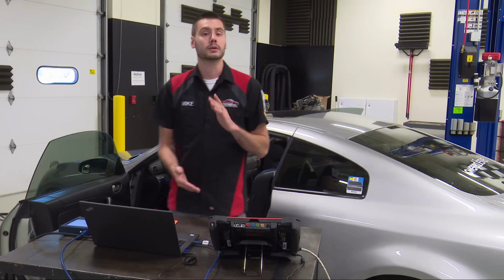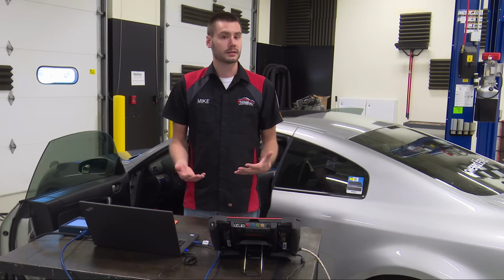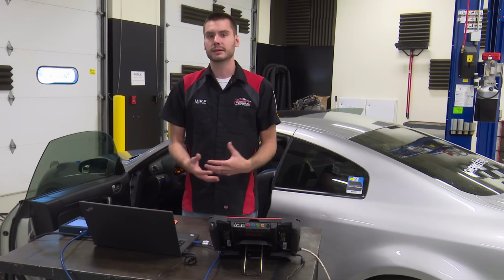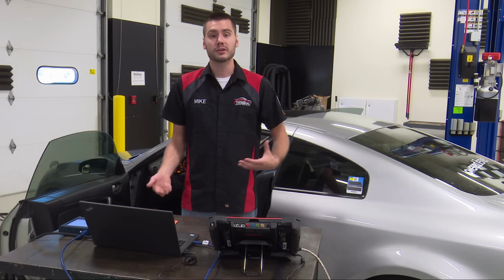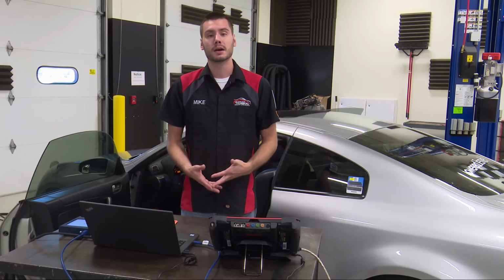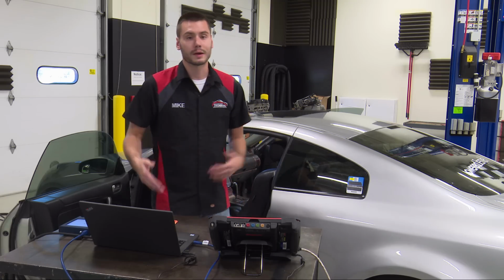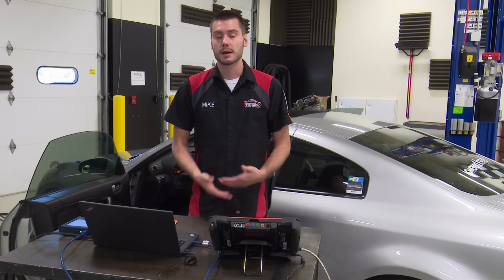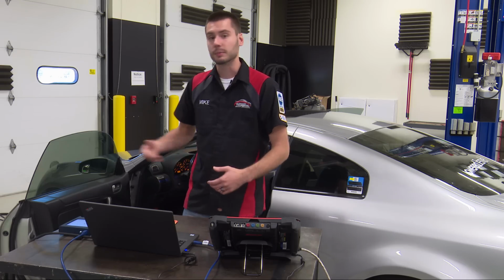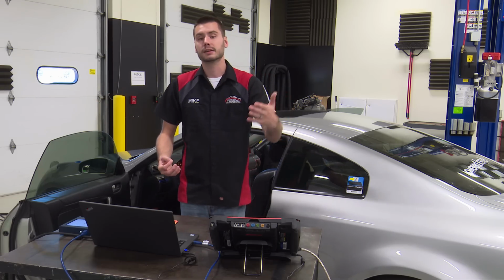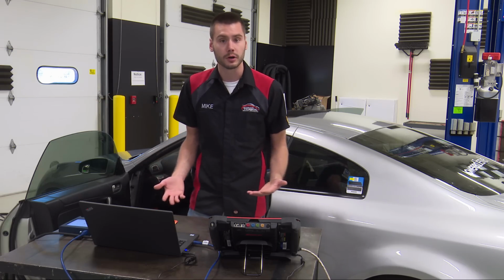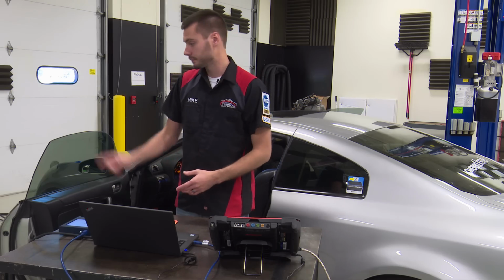So what can we do? Well, we're dealing with an electric motor, right? We're dealing with something that we deal with all the time. Every time we start up our vehicle, every time we are running down the road, we have an electric motor in the fuel tank pumping gas for us, right? Pumping it up to our fuel rail. How many of you guys out there have current ramped a fuel pump before? You're looking at an electric motor.